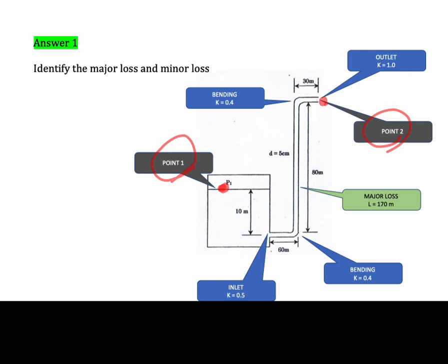According to this diagram, we know that at inlet here, we have inlet coefficient, which is K equal 0.5, and the outlet here is K equal to 1.0.